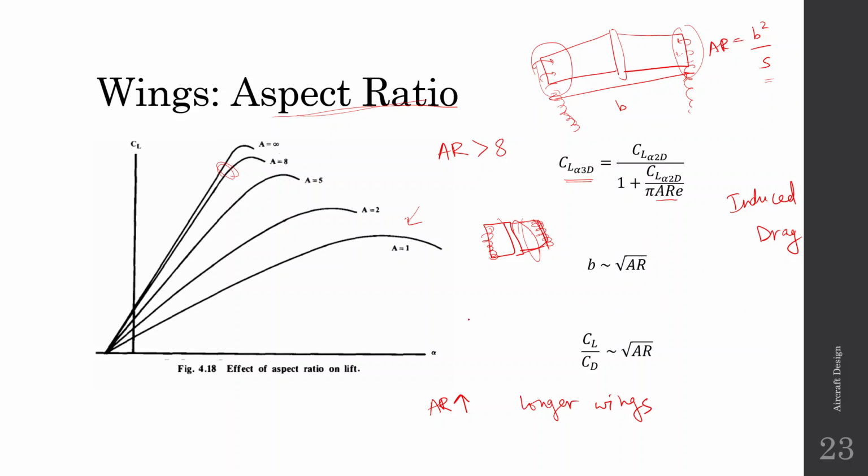But if your wing is very long, then towards the tip there will be vortices, and you cannot avoid that. But you get a large section of the wing which is vortex free and which generates lift at the same level as the aerofoil. So the CL is going to be similar to the aerofoil.